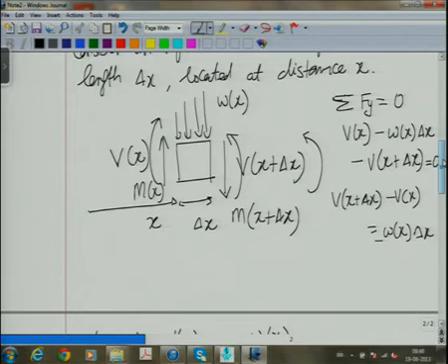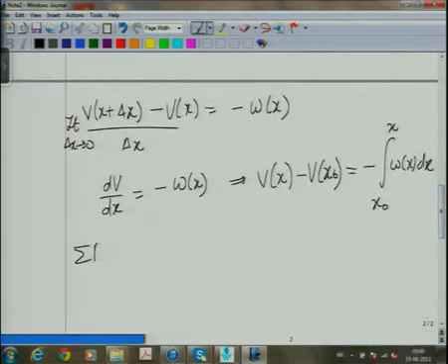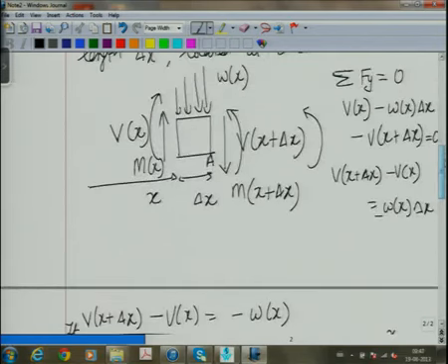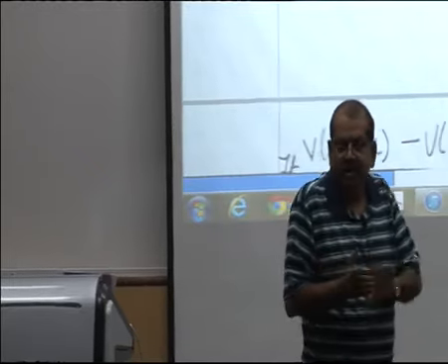So let's take the moments about, let's call this A. Actually I should either take moments about A or about B. What is the reason for doing that? So that one of the shear forces does not contribute. If I take the middle point, both of them will contribute, it will add to my work slightly, nothing more.